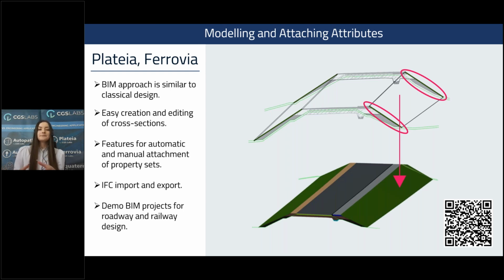sections. And when drawing cross sections, it is important that we have planimetric quantities for all the elements that we want to draw as 3D solids, and then we can draw the 3D model with just one click. So those of you who are seeing our software solutions for the first time today maybe wonder, okay, what is this planimetric quantity? Essentially, it is a hatch that can be used to create a quantity takeoff report and draw a 3D model.